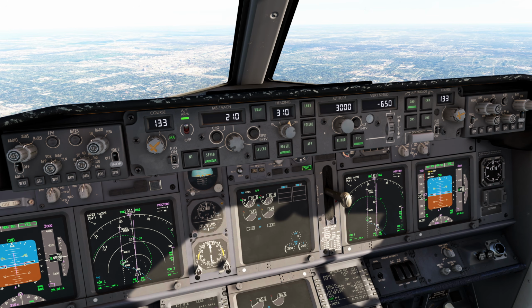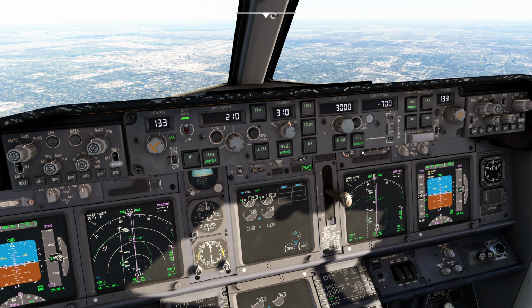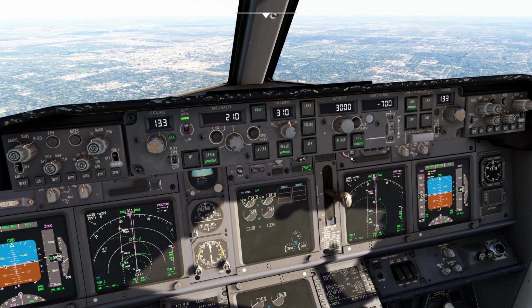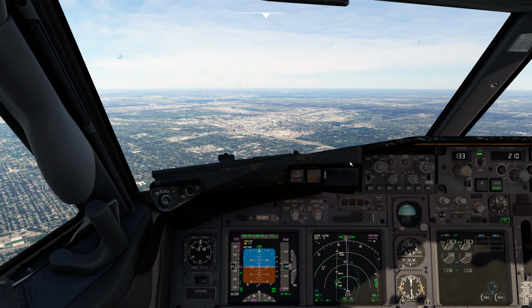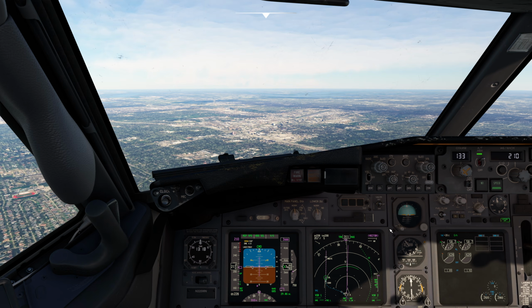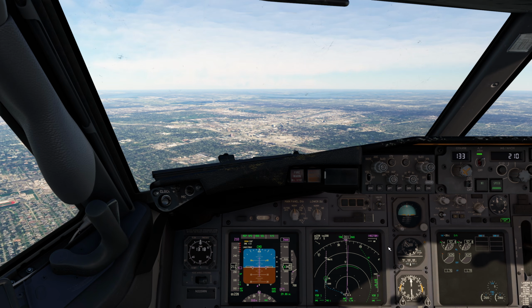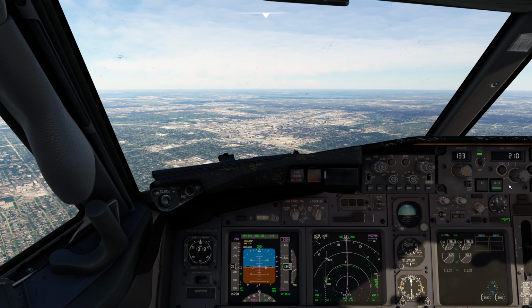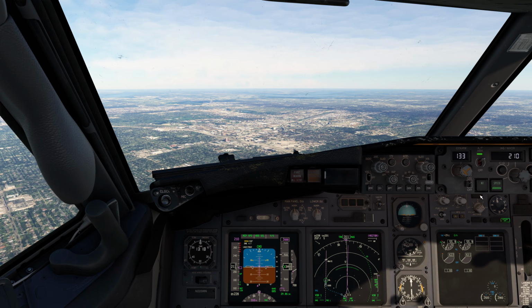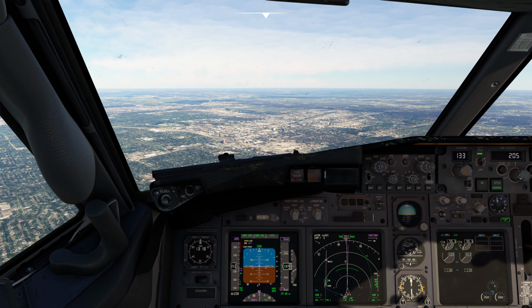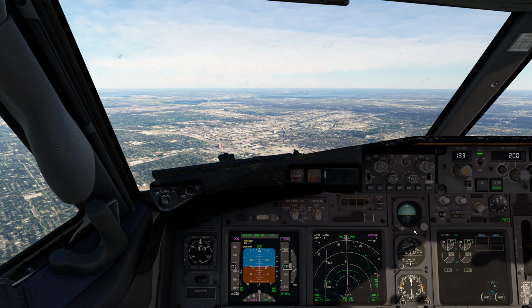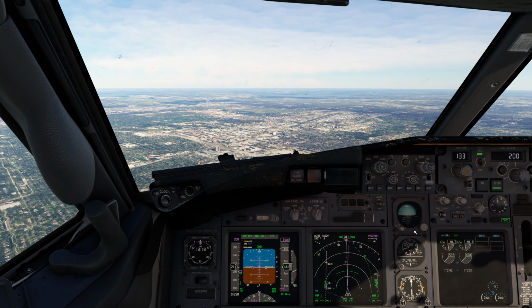Spirit Wings 2729, radar contact. Spirit Wings 2729, roger. Climb and maintain 10,000. Climb and maintain 10,000, Spirit Wings 2729. Okay, let's bump the speed down to 200 in case he just gives us that turn straight into the localizer there. And we'll go flaps 5.